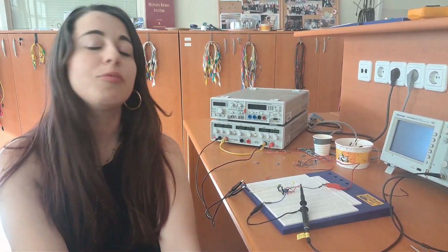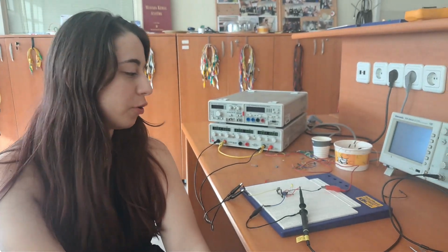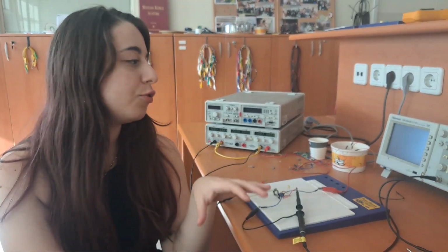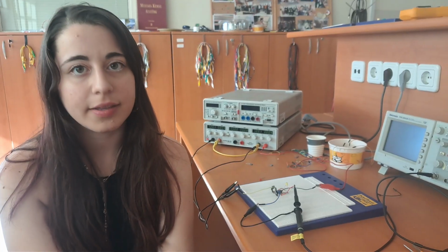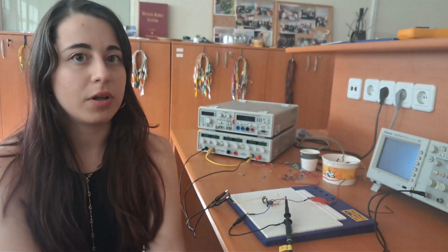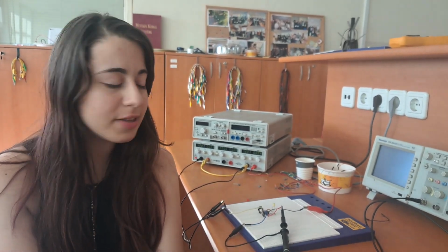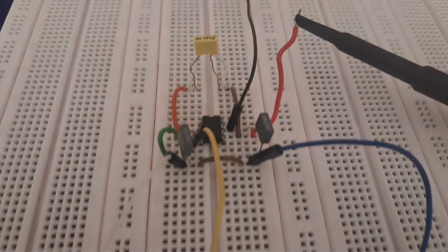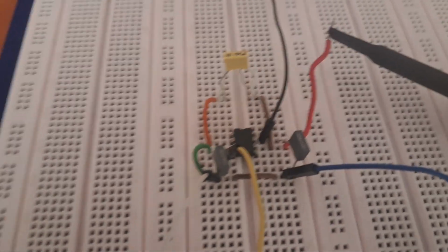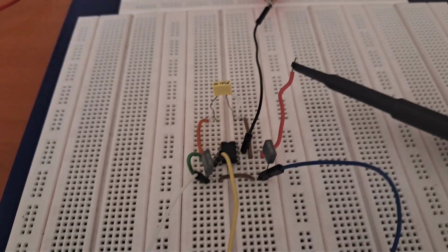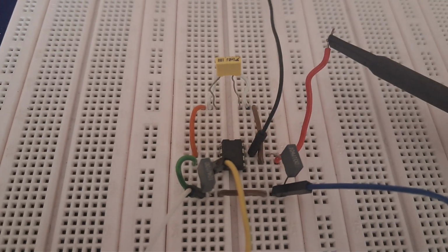Now we came to the last part of the project, the last part of the experiment. Through these conditions, we never considered the fact that there's an input bias current of the op-amp. We're gonna calculate that, and we're gonna subtract it from our previous results, so we have more correct calculations. To be able to calculate the input bias current, I simply removed the photodiode, so the only current going through the capacitor is the input bias current of the op-amp.